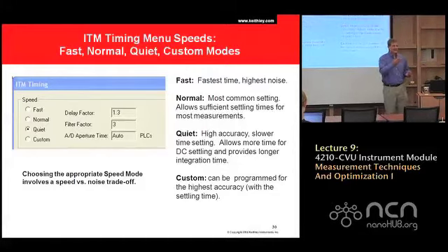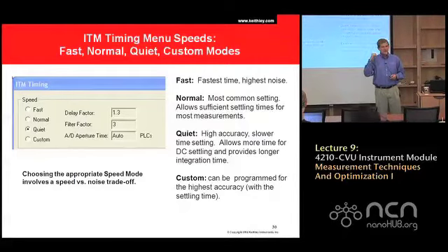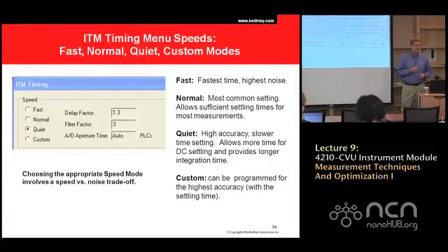That's your time factor in Johnson noise, right? But on 1 over F noise, as we go to lower frequency, the noise actually increases. It's a different noise phenomenon. So Johnson noise is related to the square of the aperture time, or how long we look at the signal, and white noise is also related to the square of the aperture time. So that just happens to be a similar relationship on those 2 different types of noise.